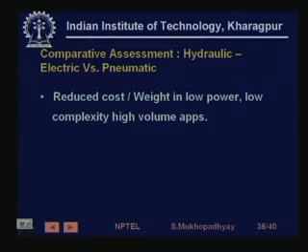So, there you see these individual tools do not require high power, there is no complexity, and the general jobs are like screw driving, clamping, etc. But there are a large number of operator stations. So, what happens is that you can have a very low cost implementation of controls, because the major equipment, that is a compressor, regulator, etc., can be shared over this number of applications. So, you must have a high volume application, and the performance requirements are very ordinary.